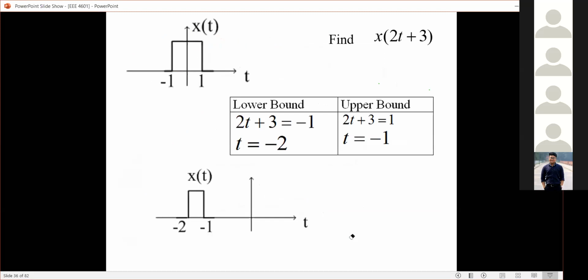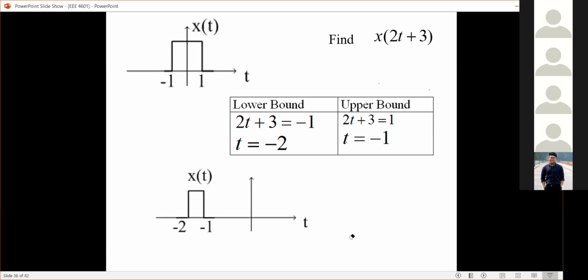Now I am giving you a shortcut technique to sketch your signal when performing these two operations simultaneously. That will help verify whether you are approaching in the correct way or not. Your shift can be in the positive or negative direction, and your scaling can be compression type or expansion type, but in all cases this technique will be applicable.